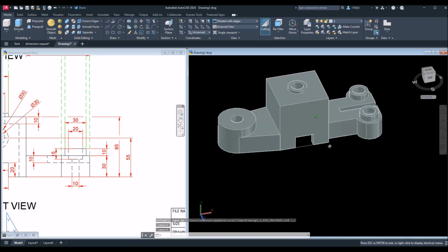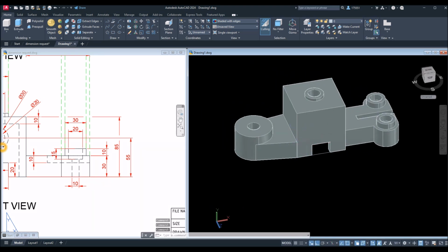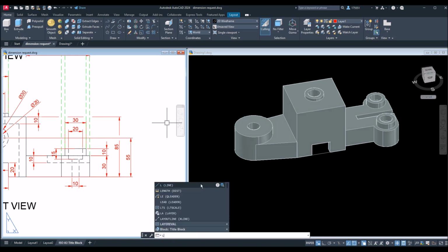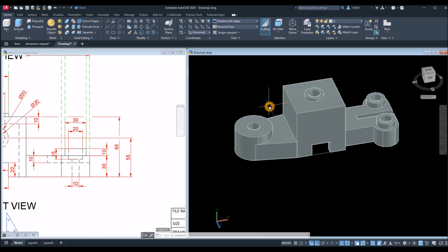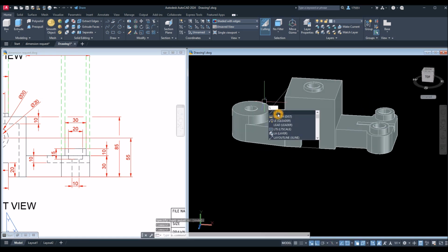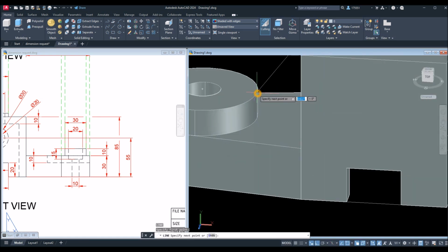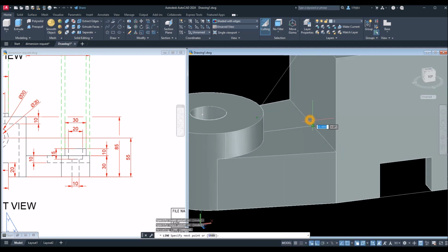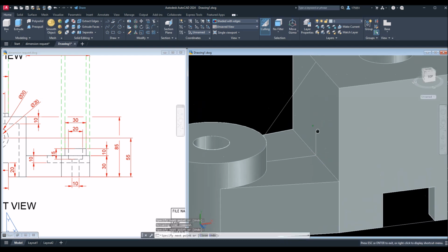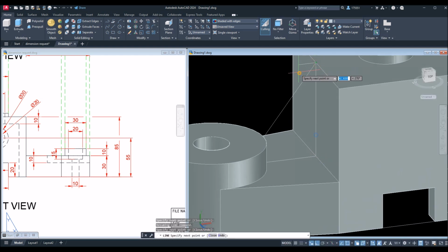And the last thing we're gonna do is the wedge. And the wedge is attached to the midpoint here, to the midpoint or to the quadrant of this circle here. So L for line. Midpoint to quadrant. Another line from endpoint to quadrant. And then go across, hit that midpoint, and hit that endpoint.